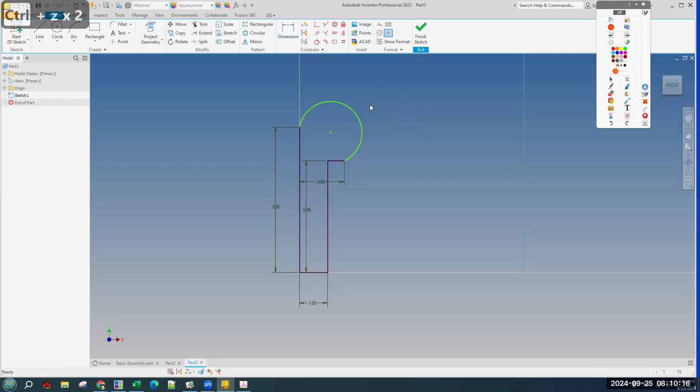Also, if you make the arc start in the wrong direction and type 0.208, it will still be wrong. And this is why arcs are finicky and a pain. As long as it's going in the right direction roughly and not too far, the dimension is 0.208.